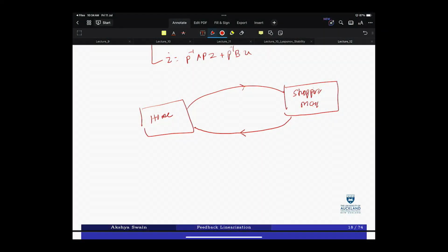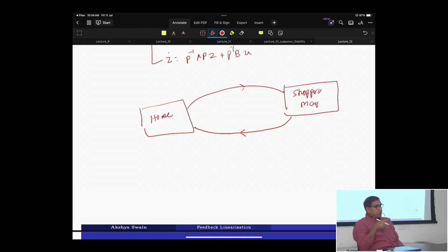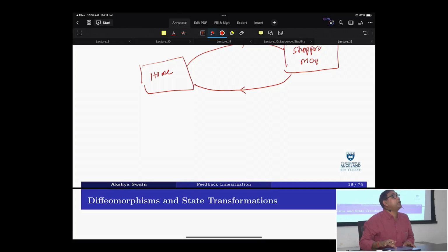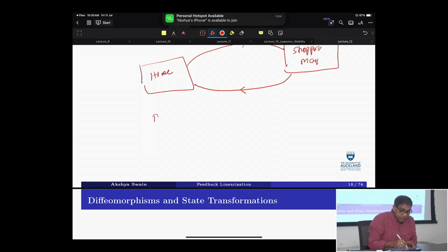In linear systems, while transforming, you consider a matrix P which is invertible. That means the inverse transformation exists. For a nonlinear system, exactly the same thing. The transformation operator which is invertible is not called a full rank matrix in a nonlinear system. It has a name: it is called a diffeomorphism.